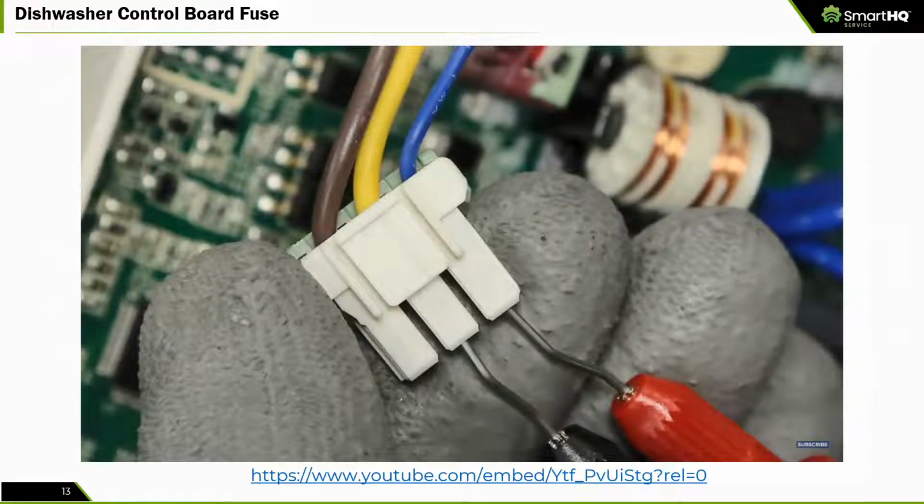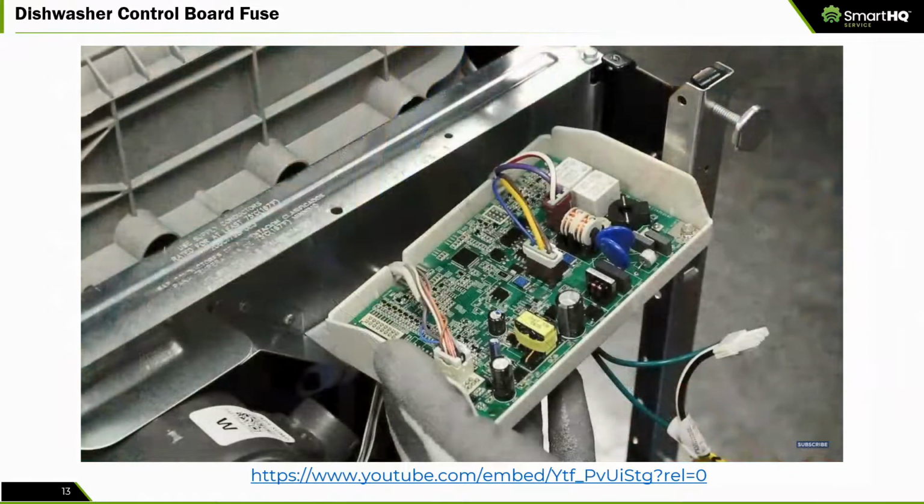As a reminder to previous training and printed material, the circulation pump has internal components such as a diode and rectifier, which make diagnosis near impossible. The result of complete diagnosis is, if the fuse is open and the drain pump resistance is not correct, replace the fuse and the drain pump. If the drain pump checks correctly, replace the fuse and the circulation pump.